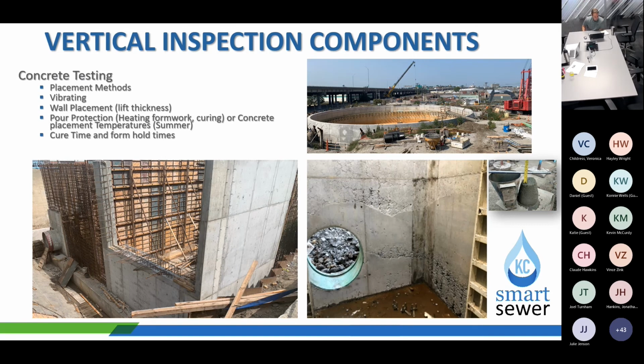So understanding those, and then you have pour protection. In the winter months, is the concrete coming out too hot? Does it need to have ice in it? In the winter, is the space heated? Is the concrete heated? And then how all this stuff is cured. A lot of these specs have a lot of different requirements or available options for curing concrete. So have the conversations with the contractor: how are you guys planning on curing this? Is it going to be water cured? Are you going to use a liquid cure? Are you going to hang burlap on the walls or leave the formwork on for a certain period of time? There's a lot of different things that these contractors can do, and you just got to make sure that what they're planning is acceptable.